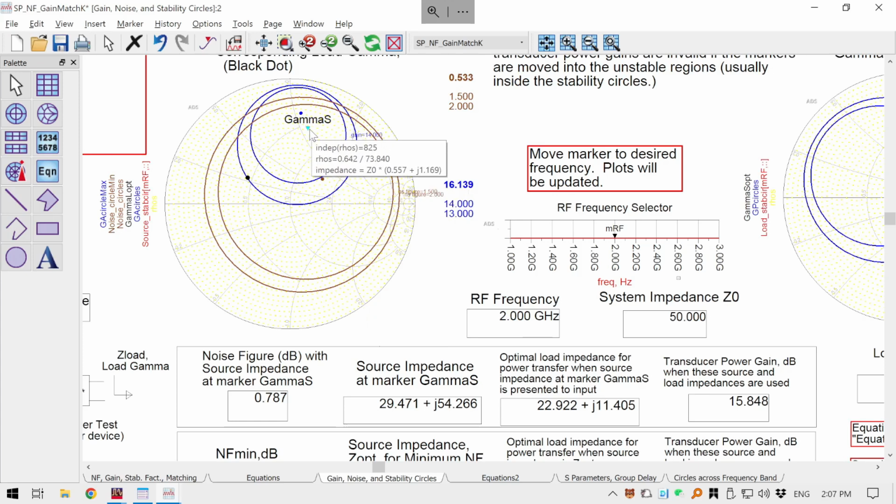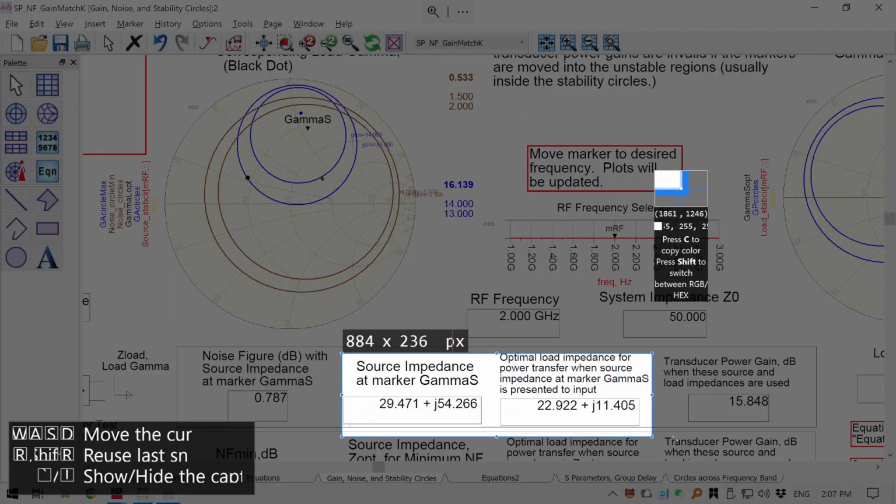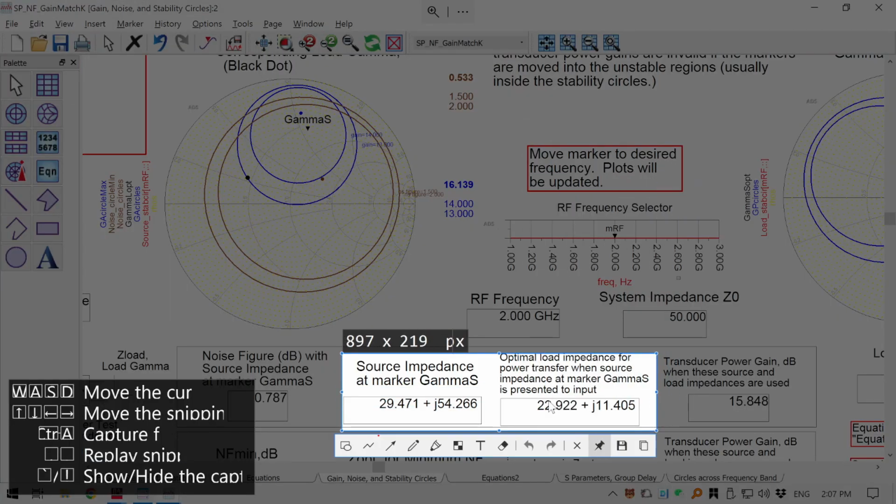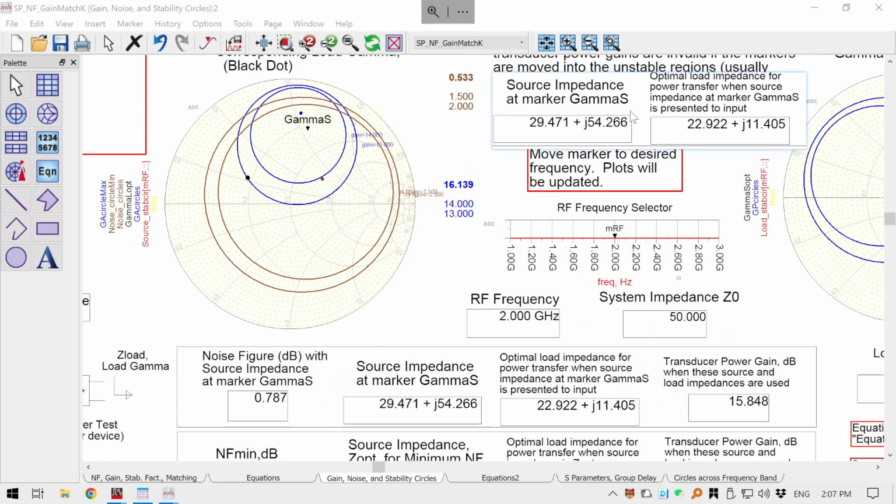Okay, so once you know this, the designer will automatically give you the source impedance and load impedance you need to have this noise figure and gain. So I will just highlight this for our further impedance tuning. The next step we are doing is creating the microstrip lines to convert the 50 ohm impedance into our required impedance. After we create this microstrip line, we can take a short break.